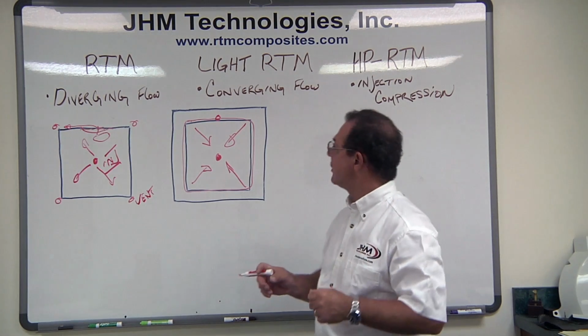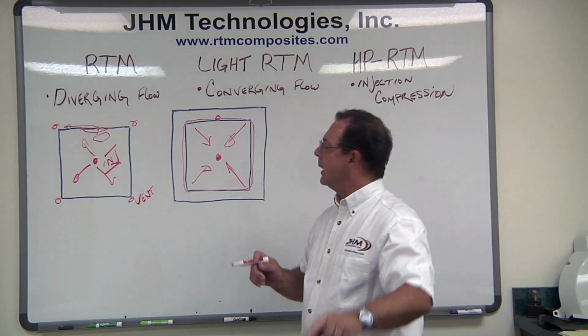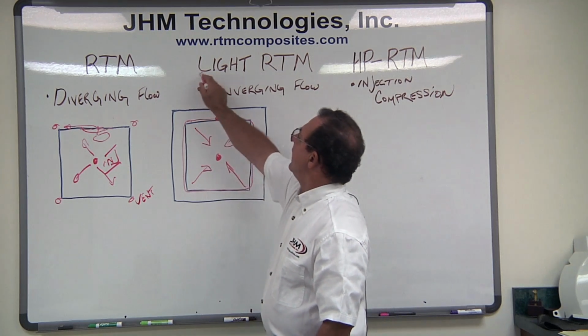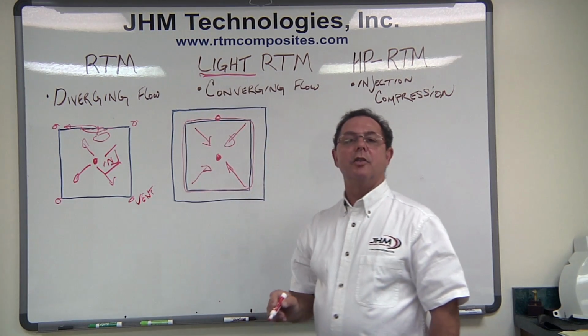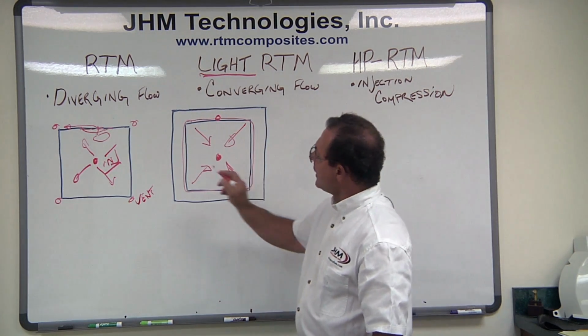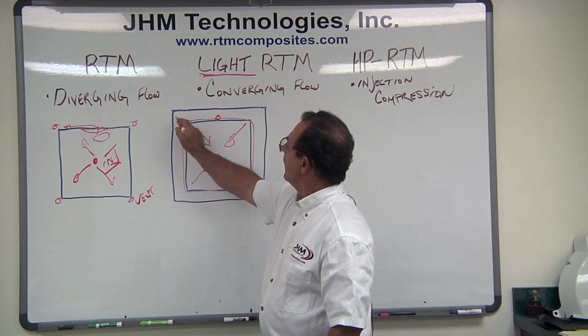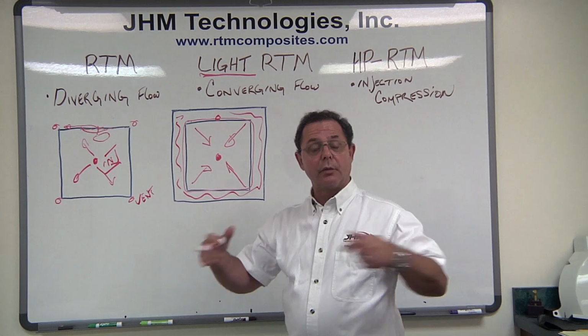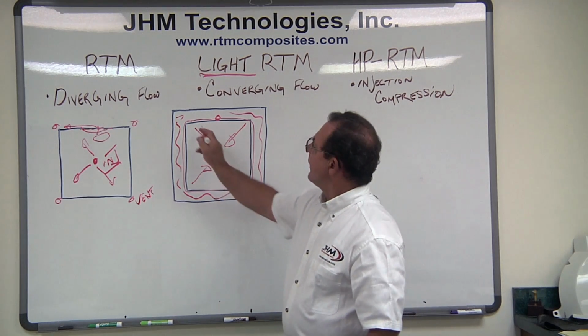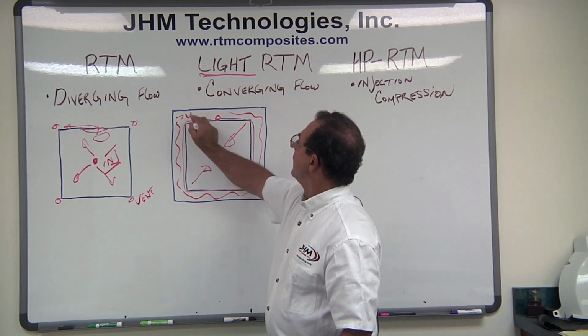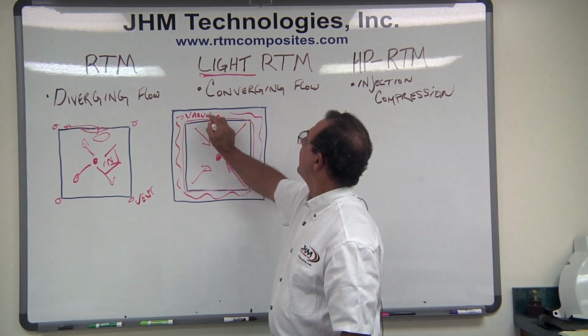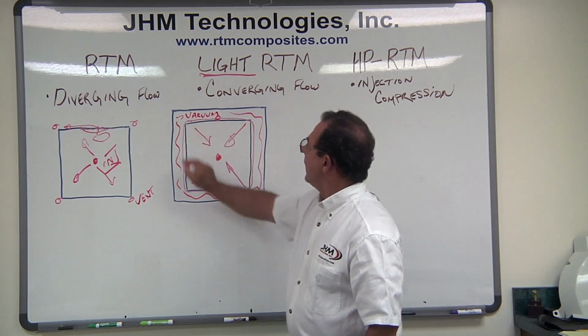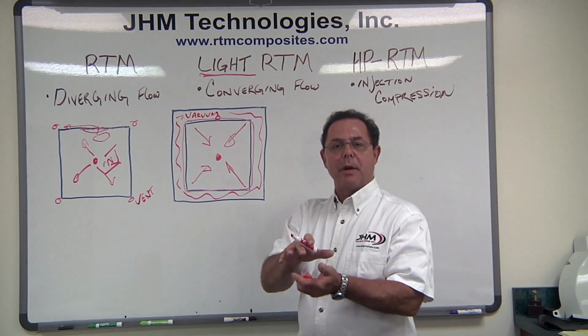Very interesting. The other element that is different is that we have this area surrounding the mold cavity of extra mold surface, which is a flange. In that flange, we will pull vacuum, or create a vacuum, and that area acts as a clamping force.